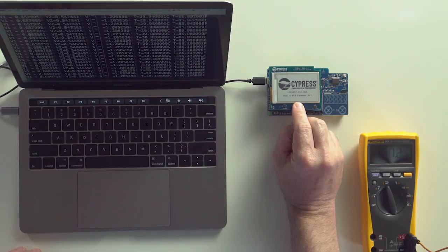What happens if you have a noisy power supply? Well, this whole thing is dependent on the measurement of the reference resistor and the thermistor being taken at exactly the same supply voltage. If the current changes because of the power supply noise, you'll end up with a less accurate reading. The averaging that we're doing in the ADC helps to filter out the noise, but I'd like to change it so the system is not referenced to the external analog supply.